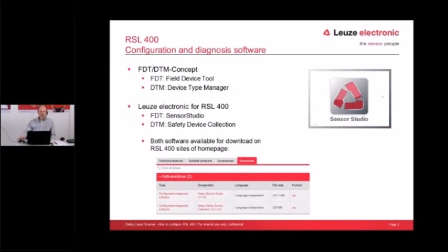The way this translates into our Leuze world is that we use Sensor Studio as the field device tool. You can also consider this the framework where the software is running. And we use Safety Device Collection as the device type manager. This is the additional tool we have to load into the framework to actually operate our RSL 400.